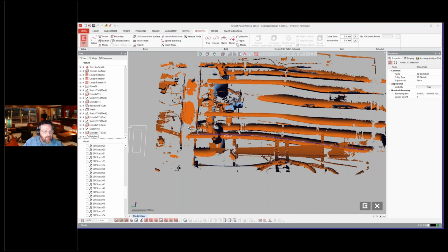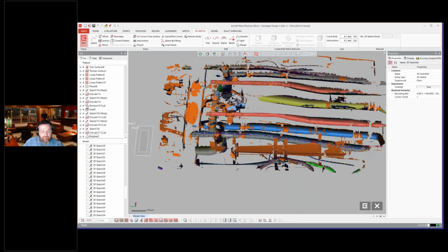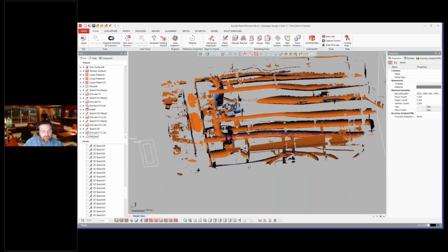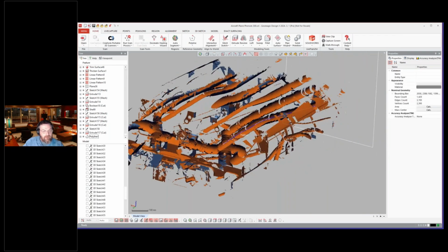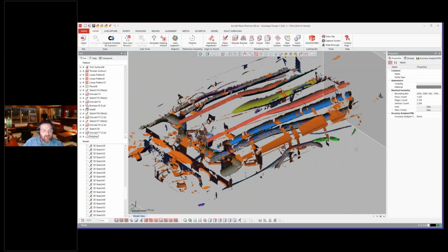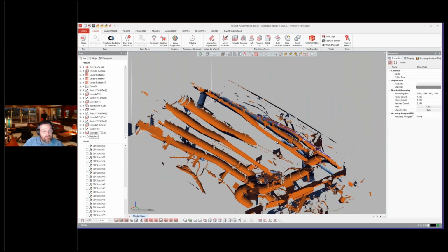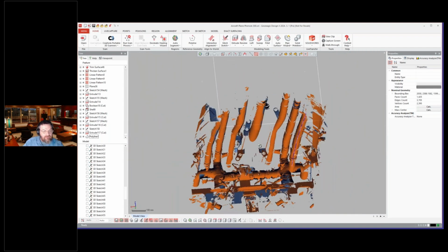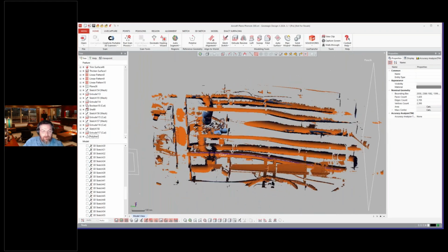And then I can put a plane on the end of my polyline, normal to a point and a vector, and then create a sketch and sweep it along that. Very simple to do, right? But I just wanted to show that's how you would do it manually, but that's how the software with the pipe wizard is actually able to extract that for you in here.